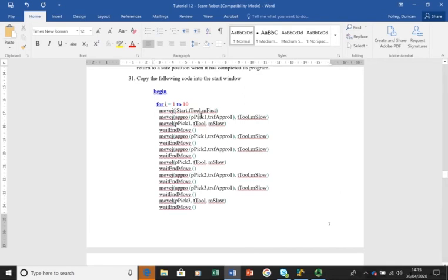We want it to approach just a little bit above, vertically above, hovering above it, and then vertically go down towards the part and pick it up. So we have an approach point, and the value of that is set in this variable here, which we've called TRSF approach 1, and we're going to say that that represents minus 15 Z,